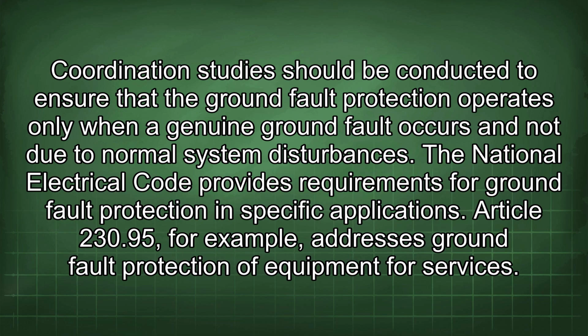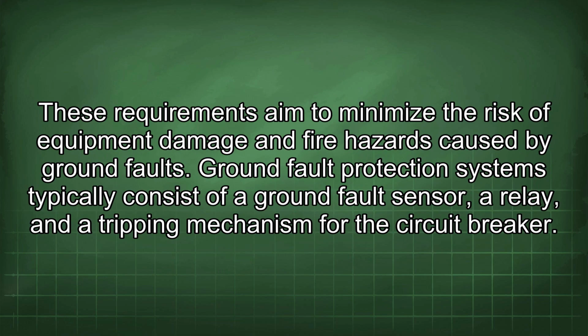The National Electrical Code provides requirements for ground fault protection in specific applications. Article 230.95, for example, addresses ground fault protection of equipment for services. These requirements aim to minimize the risk of equipment damage and fire hazards caused by ground faults.